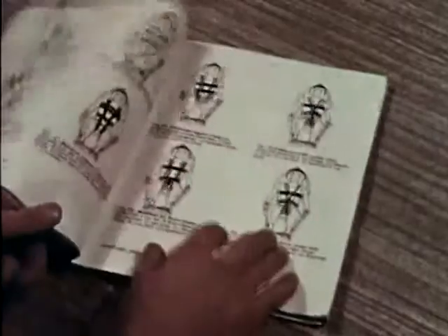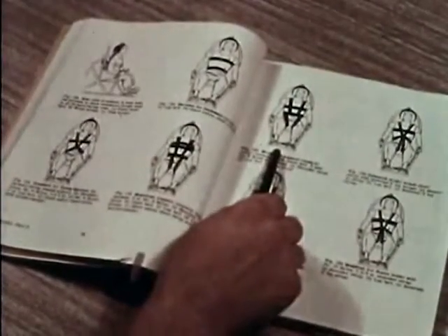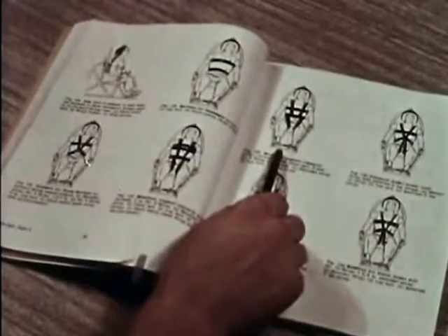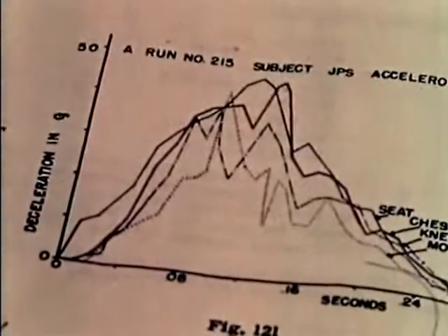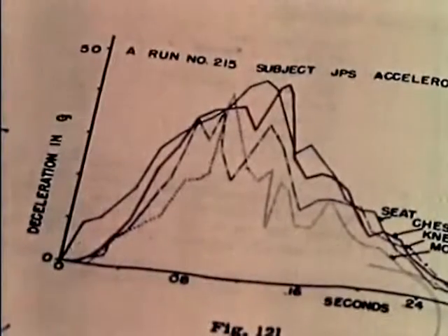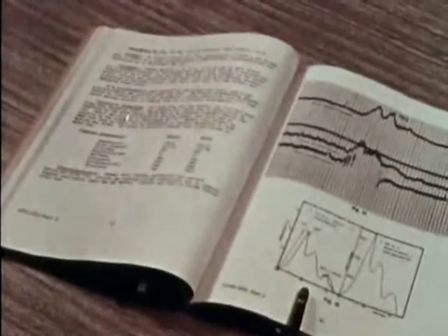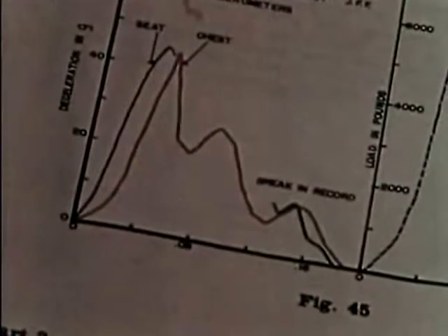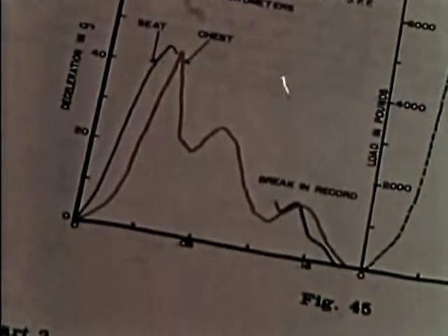In this study by Stapp, tests were made with human beings carefully supported by specially designed seatbelt, shoulder harness, and leg straps. Under such conditions, the experimenter subjected himself to a deceleration that had a maximum of 47 Gs. The deceleration endured for 0.228 seconds and had a rate of onset of 735 Gs per second. The resulting injuries were minor. When the rate of onset increased from 735 to 1,550 Gs per second, signs of shock were observed.